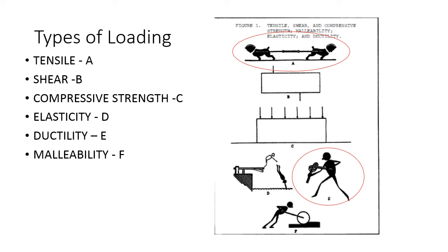Sometimes we have to worry about notch toughness if another welding code throws us over and says, hey, you got to worry about notch toughness. But for the base situation, tensile testing and ductility is what we're looking for. We want to make sure that weld isn't going to crack because it isn't ductile enough. It doesn't meet the ductility requirements for that material. And we want to make sure it has the tensile strength to hold up under a specific set of operating criteria.